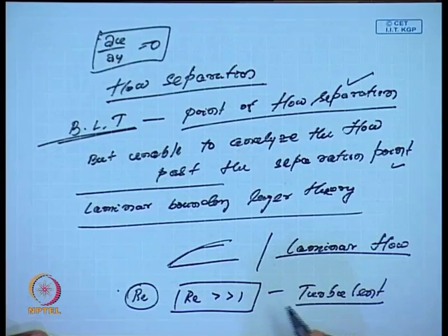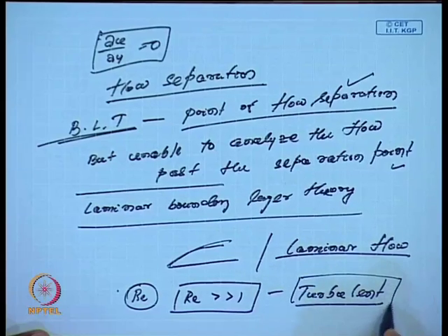The classical methods in many situations fail. However, some methods like the momentum integral equation methods can be applied, but the theory that is developed to deal with the boundary layer equation will no longer hold, and the theory has to be looked into again for the flow pattern and other things.